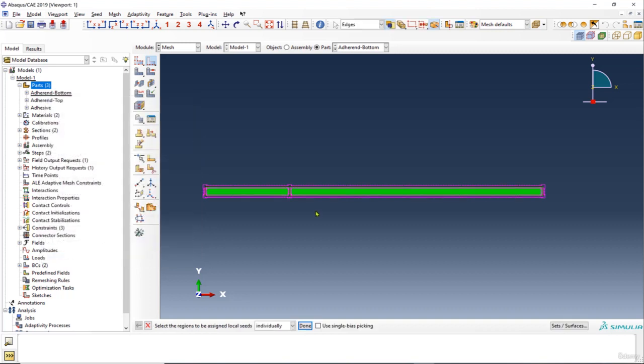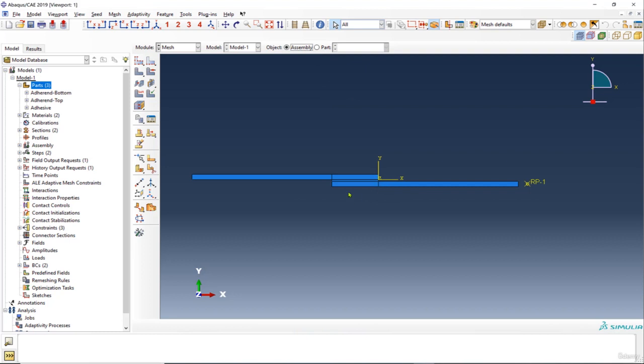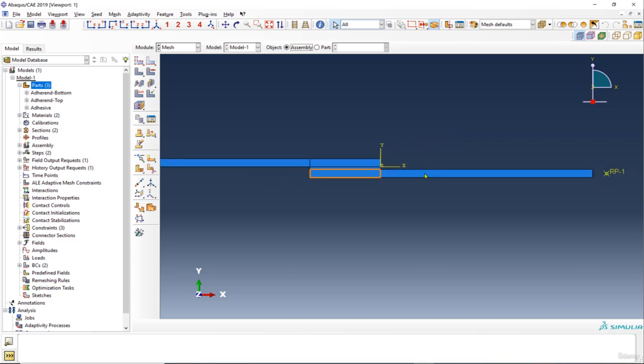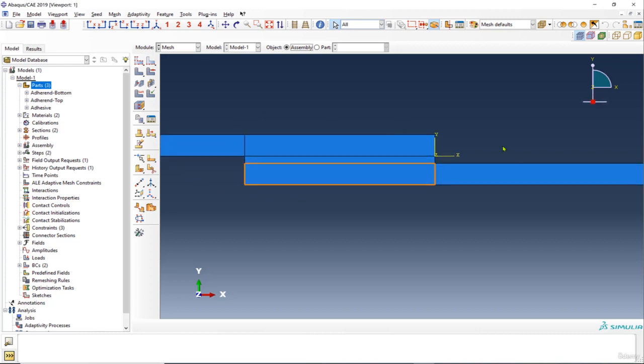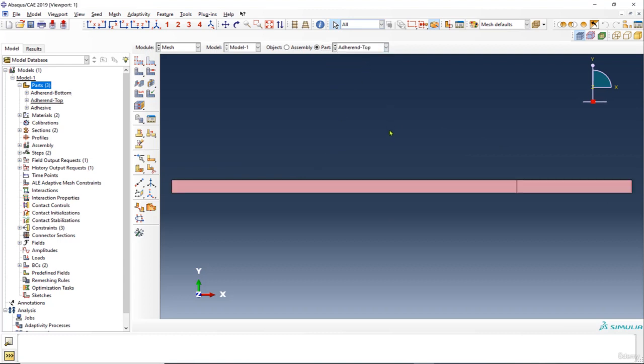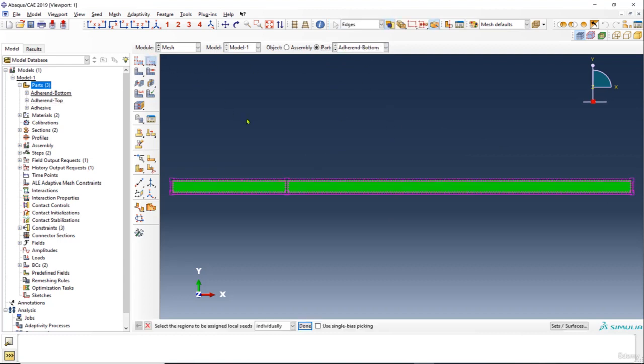But there is one point that you need to always consider when you mesh your part. If you look at the assembly here, we know that the significant part of stress is going to be in a bonding area. So we don't really need a high resolution mesh in these areas, because nothing's going to happen in this area. Everything's happening at this point. So having basically a mesh size of 0.5 in this corner, we are increasing our computation unnecessarily. So it's not really useful to have that.